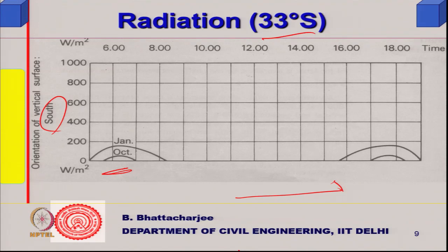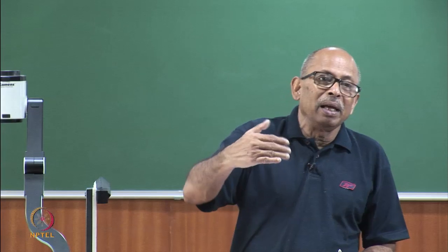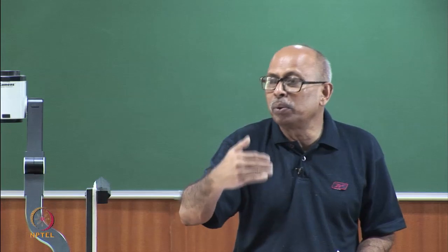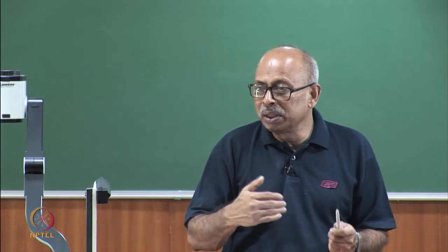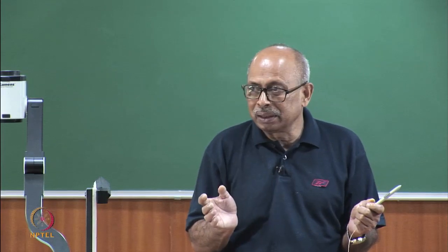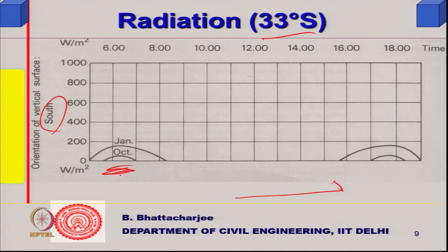In higher latitude the day is long in summer, so the sun will not rise due east but somewhat beyond it, depending upon which hemisphere it is. The day is longer than 12 hours, so even the south surface in the southern hemisphere receives some radiation in the morning and in the evening, just before sunset.